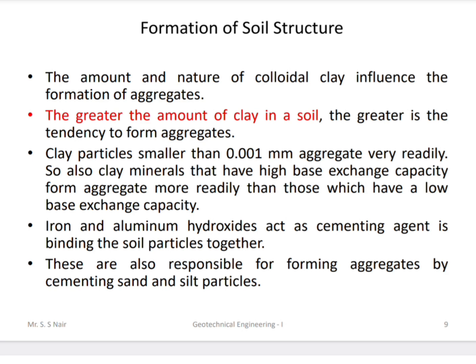Also, clay matrices that have a high base exchange capacity form aggregates more readily than those with a low base exchange capacity. Iron and aluminum hydroxide act as cementing agents and bind the soil particles together. So basically in clay these cementing agents are present which form the soil aggregates.